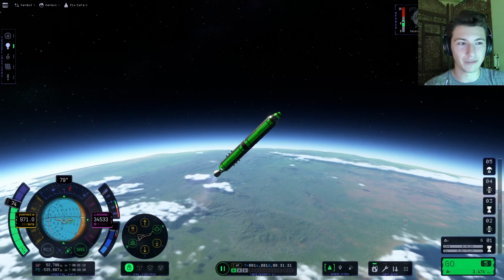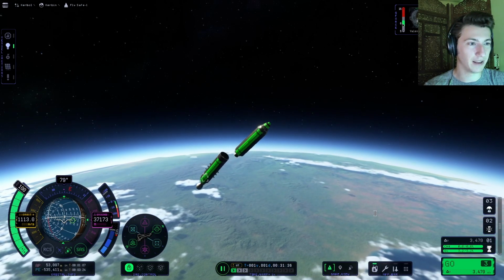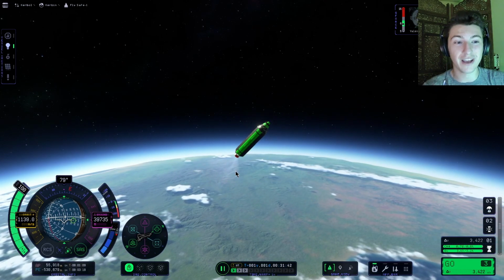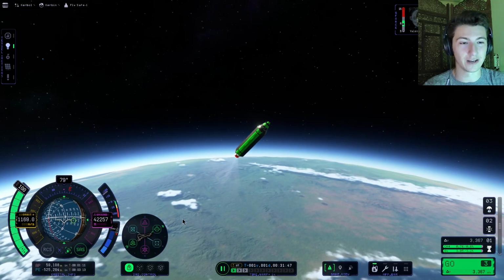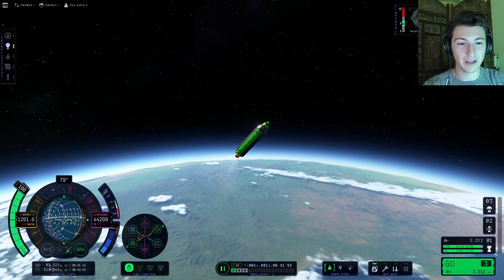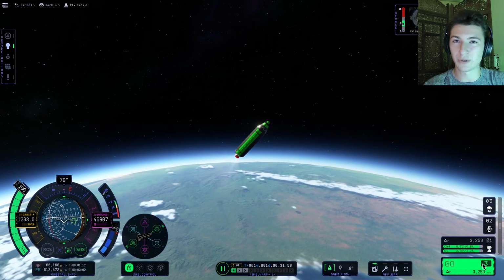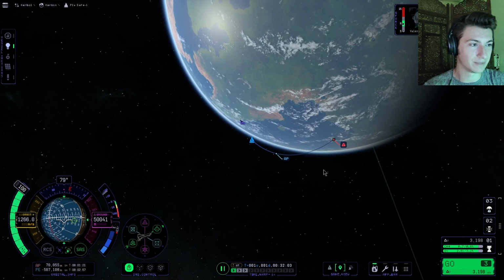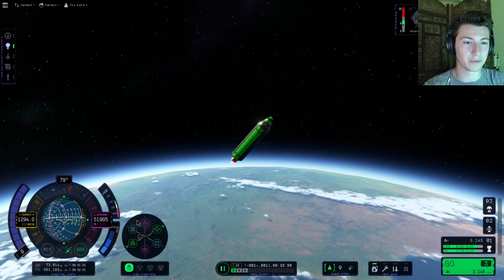We're running a little low on fuel, so this stage is about to burn out. Okay, so we separate and we activate our next stage. Now, the Terrier engine consumes very, very little fuel, so we're going to be able to burn this thing for a very long time. And what we're going to do is wait for this apoapsis number to get up to 70,000. You can see we've got plenty of fuel left. We still have 3,200 delta V. Everything is going well so far. Knock on wood. What you'll see now, our apoapsis has just exceeded 73,000 meters, so I'm going to shut the engine off.